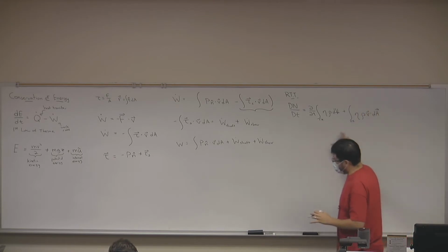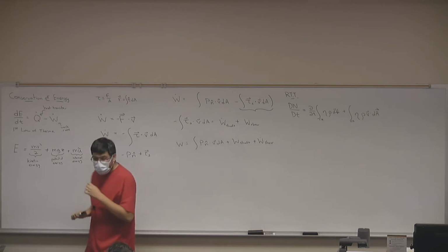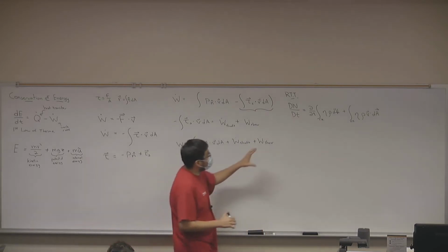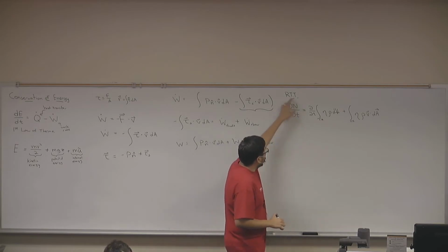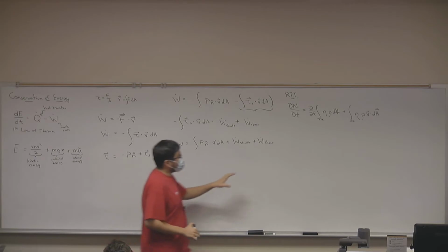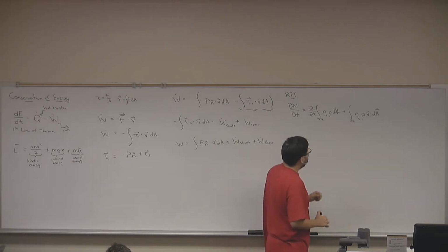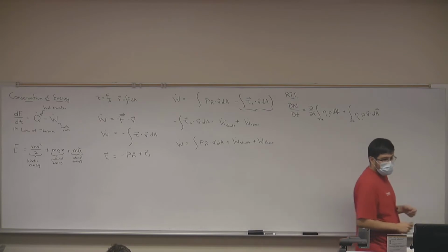And why did I derive this Reynolds transport theorem last week? Because this Reynolds transport theorem, notice, allows me to relate a law that applies to a system and express it in terms of control volumes. Now let's talk a little bit about this eta and what this N means.